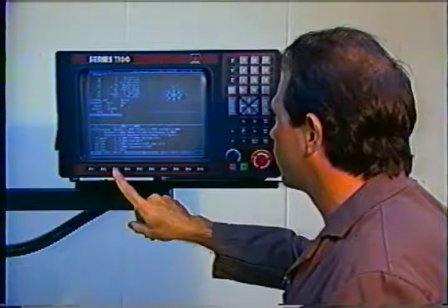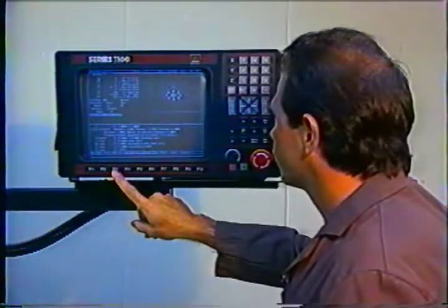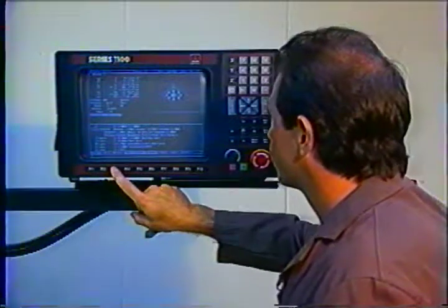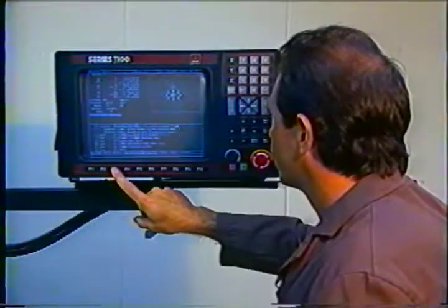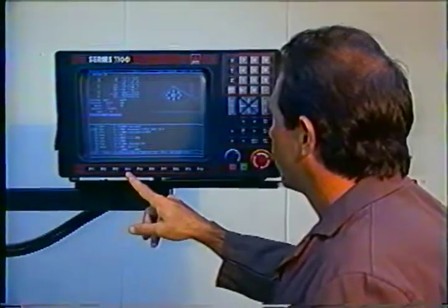I'm going to put it in a single step by motion here as soon as this pocket is done. And we can see by the numbers displayed to us on the screen that tool compensation will be active here in a second. Okay, I just went to single step by motion.